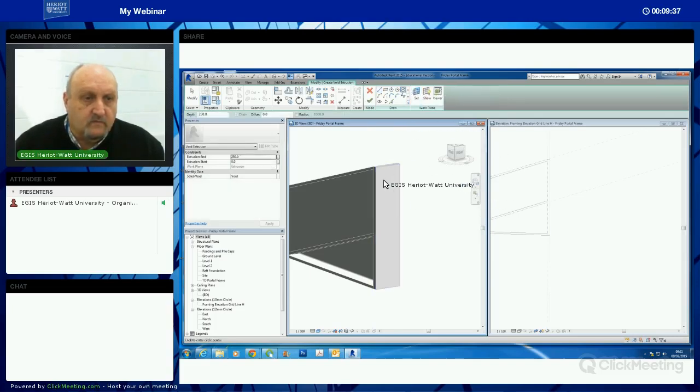I want to make some holes in this, and you can get quite fussy in here. You can go into quite precise measurements. I'm going to make mine 25mm, and I'm just going to copy that void multiple times. I have to make sure this says multiple in here, and I select it by center. And again you can get quite fussy in here with the dimensioning. And I'm just doing it by eye just to get it done quickly so you can see it. Put 3 in the top, 2 in the bottom, but all at least aligned.